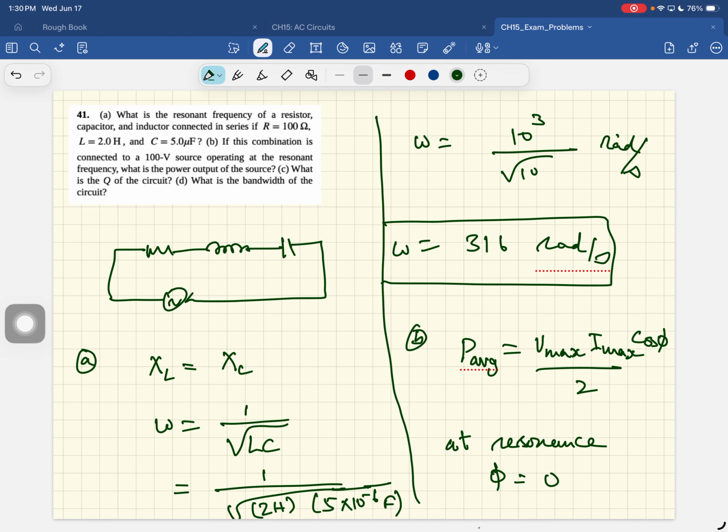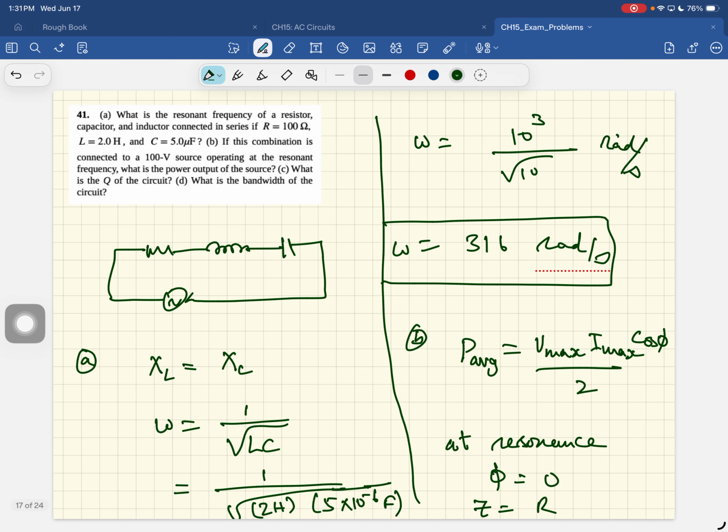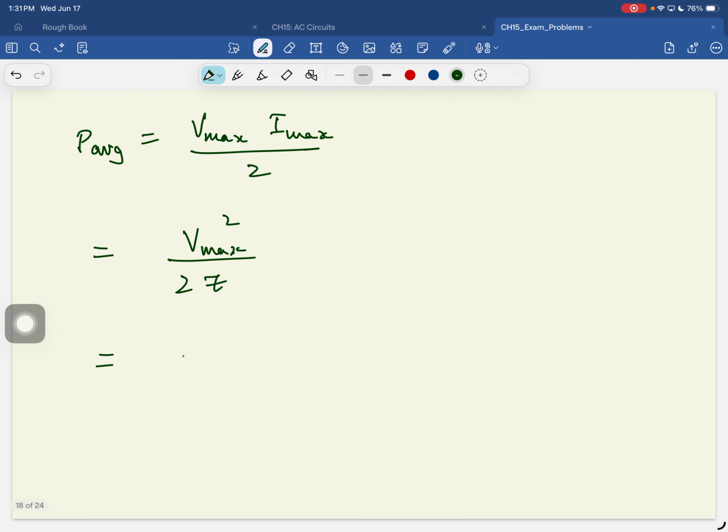All right, so if you look up, V2 is N2 over N1 times V1. Okay, so if you put RMS values, you get RMS values. This is 2000 volts, this is 110, and they give you 100 turns in the primary winding, so N2.